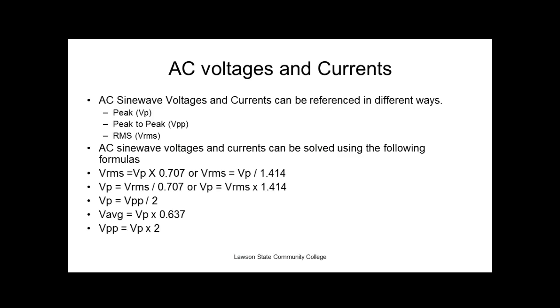All right, and just to understand it, knowing it is okay, but to do the math you need formulas. But understanding that, if I was to measure Alabama Power, I'm going to measure a lot of voltage with an oscilloscope, because what does an oscilloscope do? It shows you exactly what's there. What does this guy right here do? It doesn't show you what's there. It gives you an effective voltage, right? You understand? If you put it on DC, it gives you a DC average of what it sees. If you put it on AC, it's going to be 0.707 times whatever AC it sees. What's nice about an oscilloscope is it shows you exactly what's there.